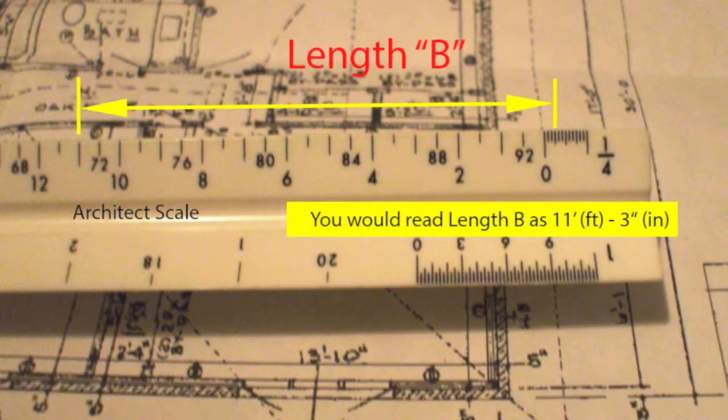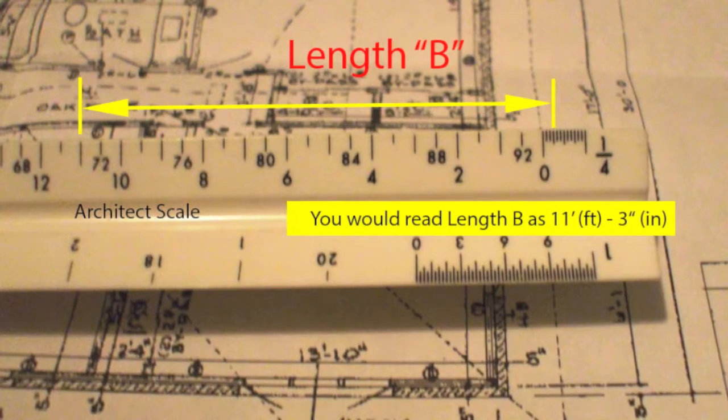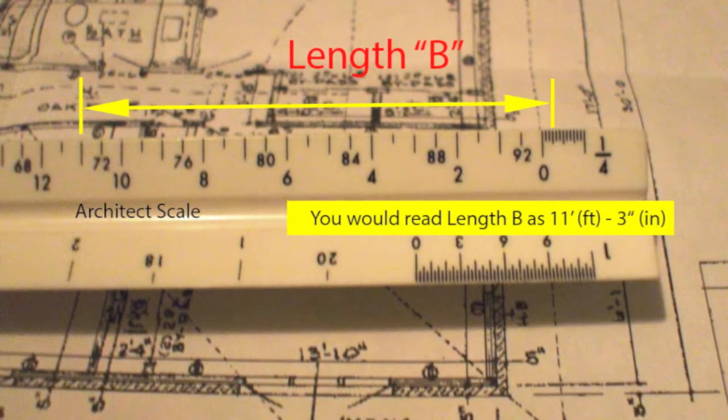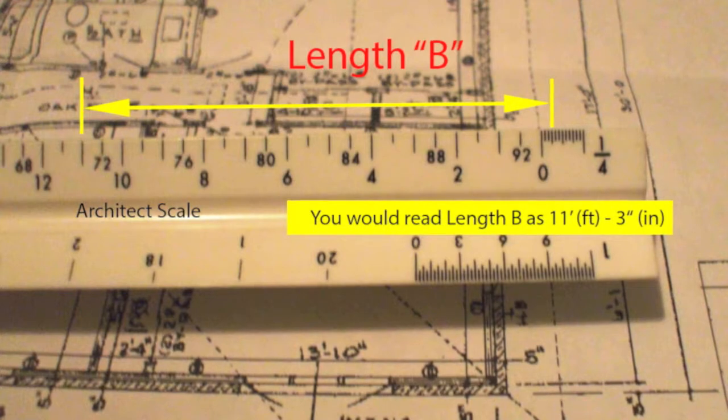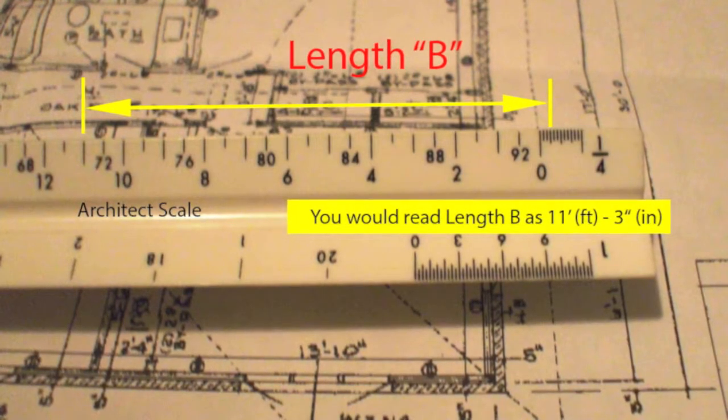From 0, simply count the number of tick marks to the right. I count 3. You read length B as 11 feet, 3 inches. Remember to use the correct ratio that matches the drawing scale you are sizing.